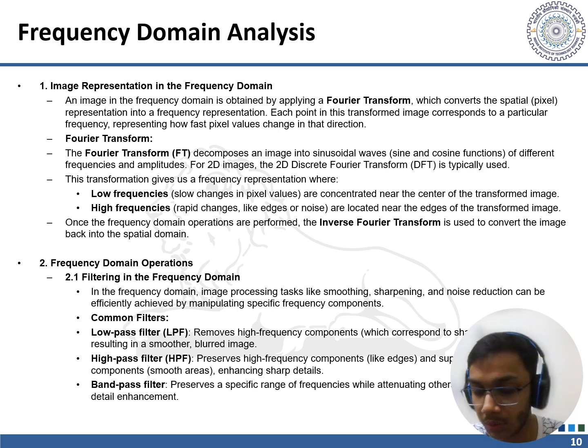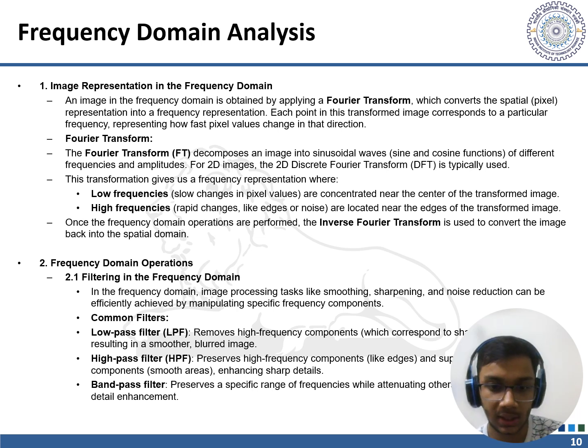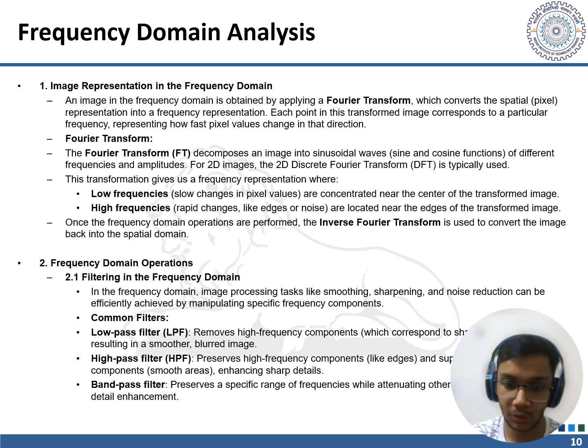It's recommended to work on either low or high frequencies, but if required, we can work on both high and low together simultaneously. In this frequency domain, image processing tasks like smoothing, sharpening, and noise reduction can be efficiently achieved by manipulating specific frequency components.